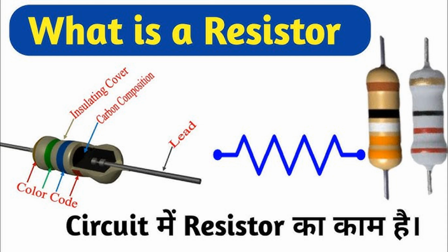Bandpass filter, BPF. Purpose: allows frequencies within a certain range to pass while attenuating frequencies outside this range. Application: isolating a specific frequency range from a broader signal spectrum. Example: in radio receivers, bandpass filters are used to select the desired frequency band for demodulation.